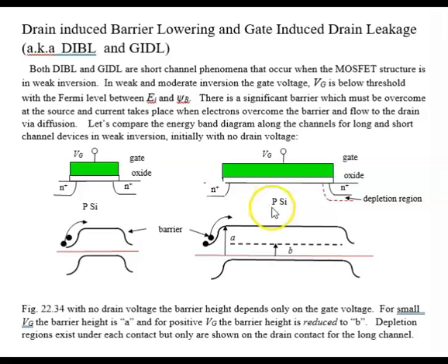So we have 0.56 plus 0.42, or about 1 volt. So the barrier here underneath the gate would be approximately 1 volt if we had flat band. Well, flat band is not realistic, so let's go to now a realistic case, and a realistic case would be, say, weak inversion, somewhere between weak inversion and moderate inversion.